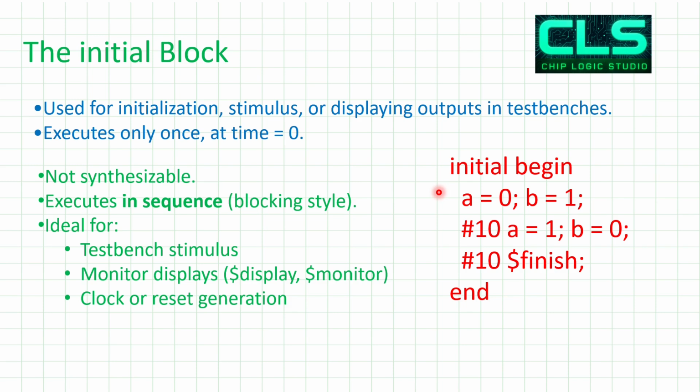For non-blocking it may change sometimes, but the initial block is about initializing everything, so mostly it will go in sequence. It is ideal for testbench and stimulus; as you see in a testbench we give some inputs, and we can use forever blocks and for loops inside this initial block. Monitor and display statements can be used here, and clock or reset generation can also be done there. So this is our first block.